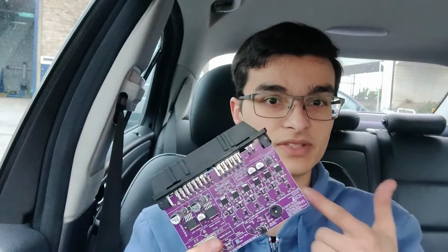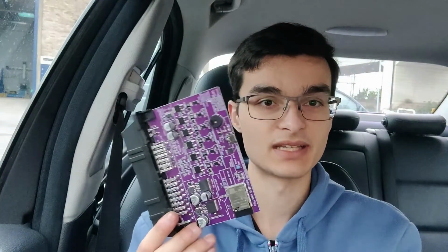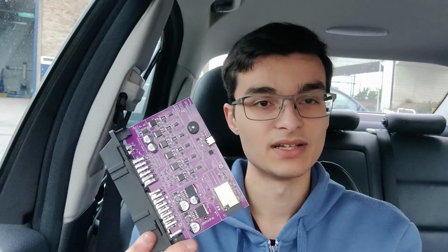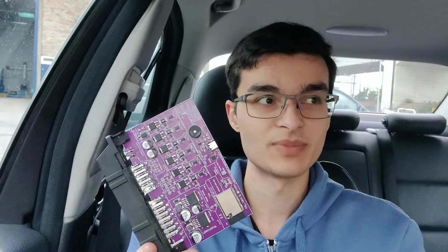So, I hope you enjoyed those two little test runs. Now, judging by how quickly the car was shifting using this controller, it clearly shows that the 722.6 gearbox has quite a bit of shifting power, just Mercedes never harnessed it. So, I think we can try in the next part to see if we can get this controller to be a little bit smarter, so that it's not so jerky changing into gear, but at the same time it can give you a really, really quick shift if you want it, or a nice slow shift like in comfort mode if you really want.